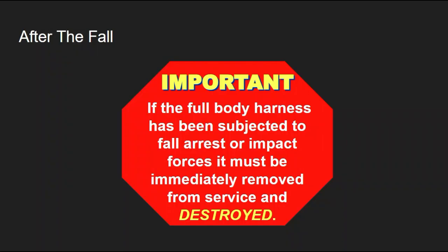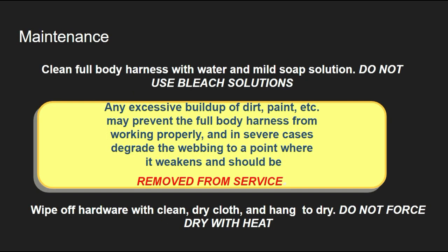After the fall. Important: if the full body harness has been subjected to a fall arrest or impact forces, it must be immediately removed from service and destroyed. Maintenance. Clean the full body harness with water and mild soap solution. Do not use bleach solutions.